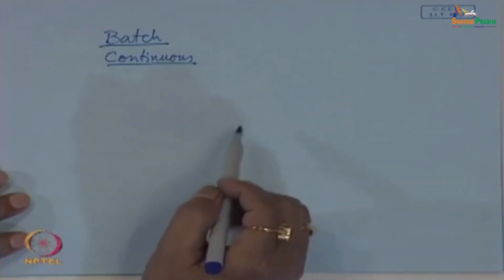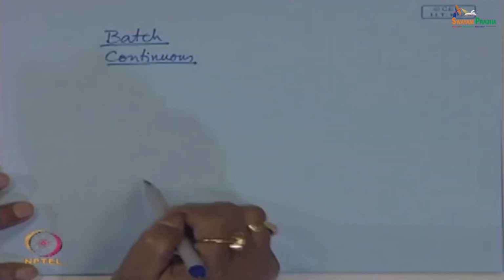So, it is carried out up to lower conversion, and then there needs to be a provision for recycling: isolation, separation and purification of the unreacted ingredients, and those isolated, separated and purified unreacted ingredients need to be recycled to the reactor. Again, in a batch reactor there may be only one vessel used for polymer manufacture.